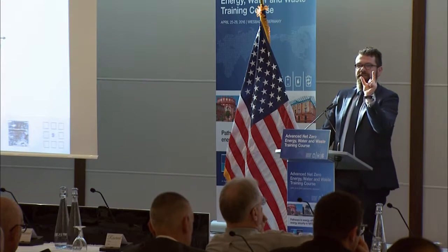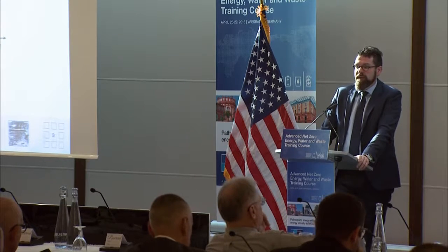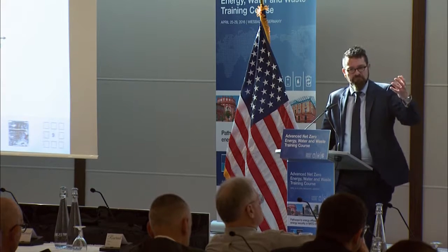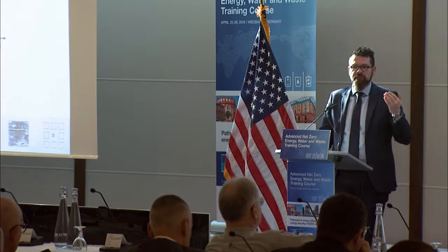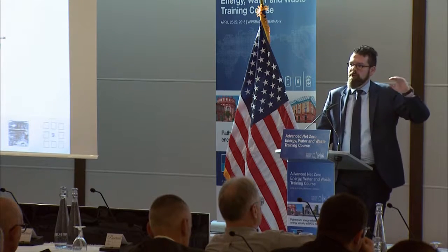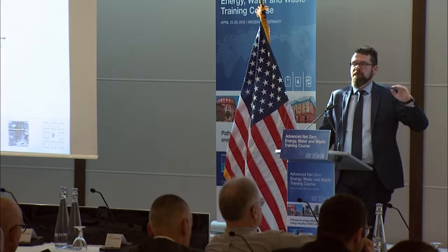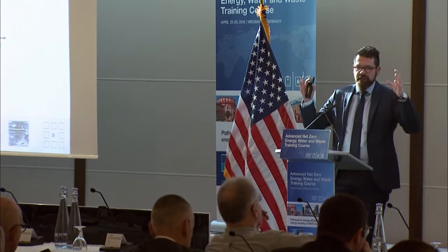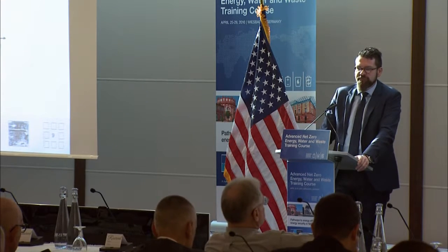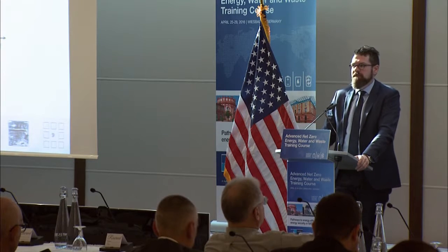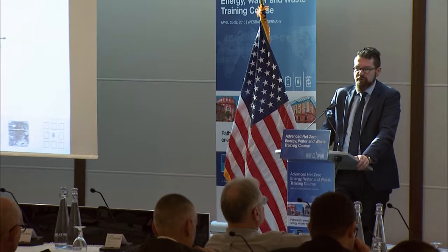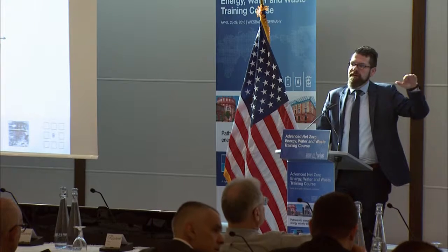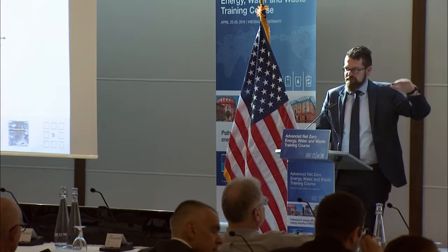Mostly this peak is a little bit tighter but higher. Then we have the domestic hot water base. There you can see this is running like a constant load through the day, depending on the domestic hot water preparation system, because you mostly have a storage heat loading system. This means if you have a shower, you have a storage of about 150 liters, and you use this water when showering or doing the dish washing or whatever, and then you reheat it again. This is quite a constant load through the day.